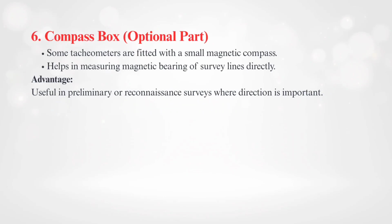Then the next component part is a compass box, which is totally optional. Some tacheometers come with a small compass box attached, and this compass helps in measuring the magnetic bearing of survey lines directly. It is especially useful in the preliminary or reconnaissance survey, where the directions are also required along with the distances. So this is about the compass box, which is optional in tacheometric surveying.